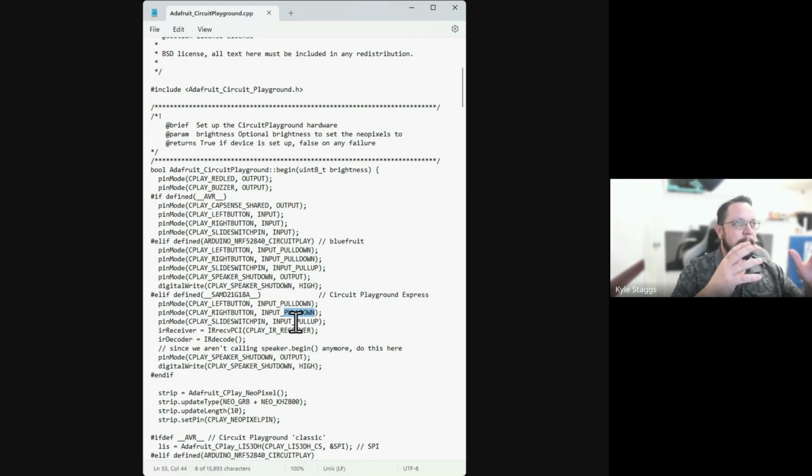So anyway, the pull up and pull down resistors are trying to do those things. So you have the options sometimes to set an input as a pull up or a pull down. The buttons are naturally trying to set to a pull down so that the value is sort of forced to be 0 so that you don't get false button inputs that trigger your code to actually run. That's the simplest way I can think of to do that.